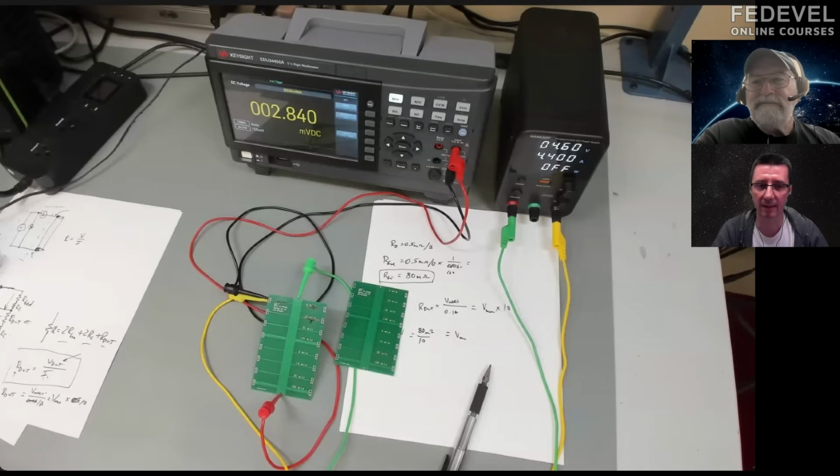And so I have another question. So often you may see Kelvin points or something, when you would like to measure current or something. What we did here, we did three different measurements. We did the 2-wire method, we did the 4-wire method in the multimeter, and then we used the multimeter as a voltmeter and used our external power supply so we can control the current.